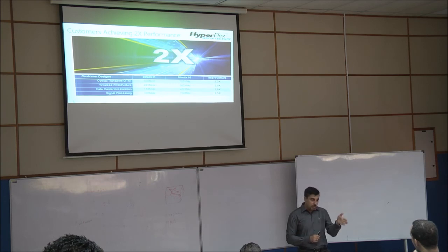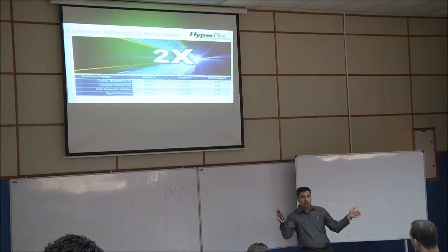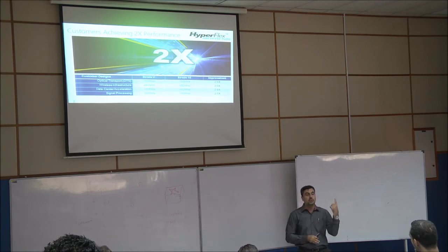So 3 means I have to put 3 flip-flops cascaded. If I put, for example, frequency X, the output becomes X over 8. Clear? Because each flip-flop divides by 2.